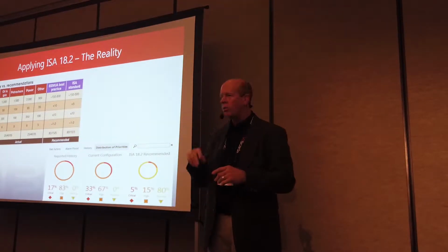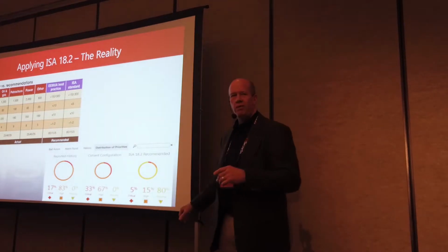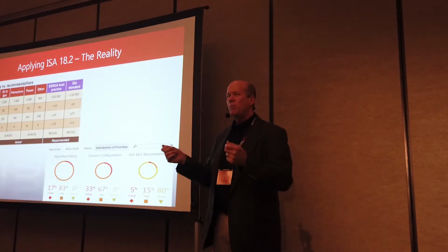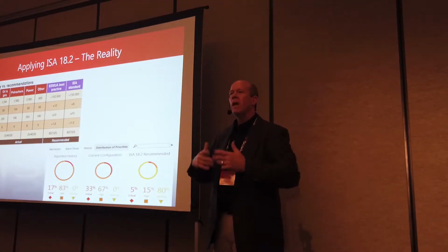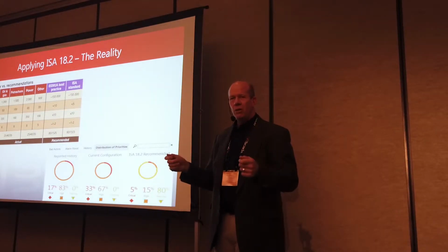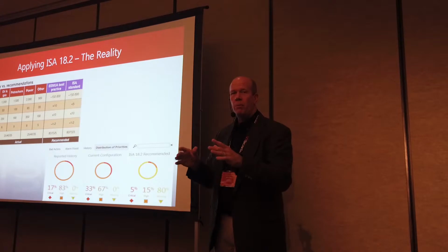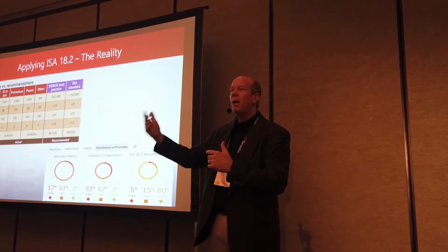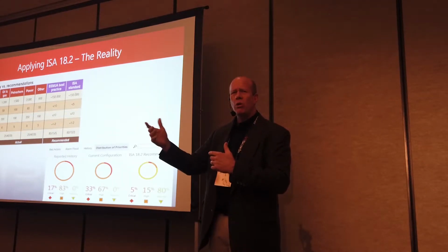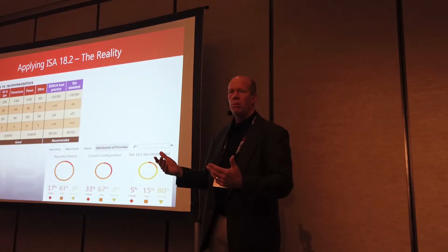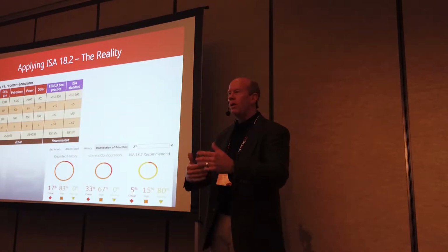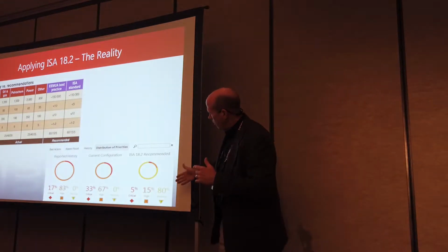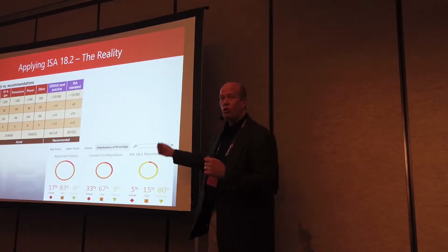They also came out with 2 other things. One would be a notice and one would be an event. So basically, we would say most of your alarms coming in are probably something to notice. If they're being processed right and distributed to the right people, they'd say, take note of this. And by the way, because this happened, you need to probably plan something next week or the week after to take some preventative action, maybe some maintenance, maybe something along those lines. Maybe look at your controls, how things are working, that it might be a problem. And if you see those things coming in more frequently, then you take appropriate action and move it up your to-do list perhaps. But you really don't want to have any more than that on your true alarms.